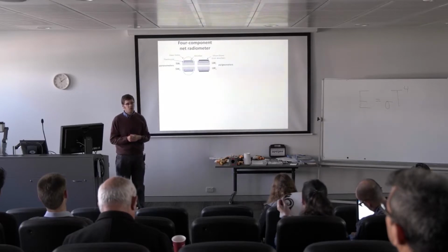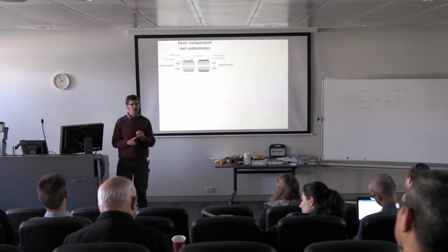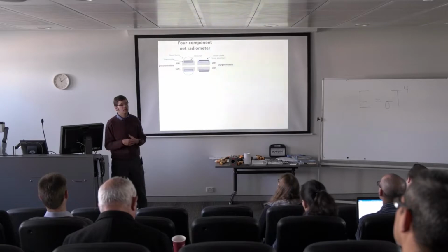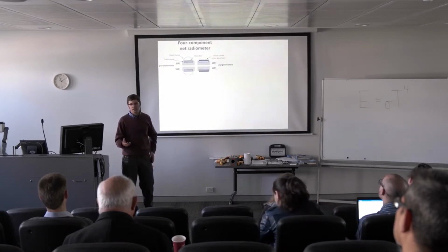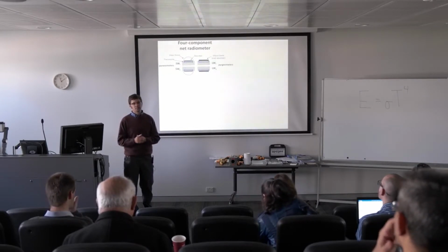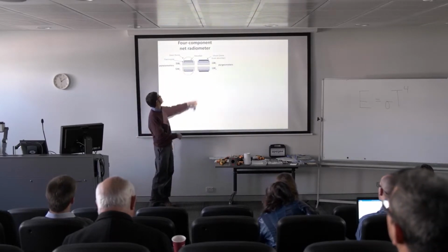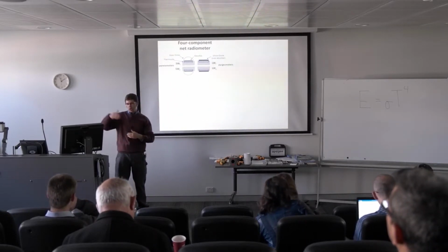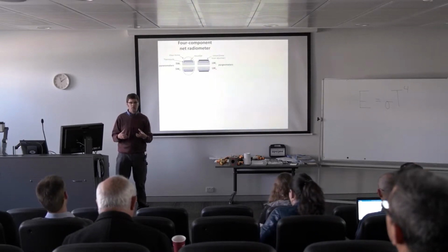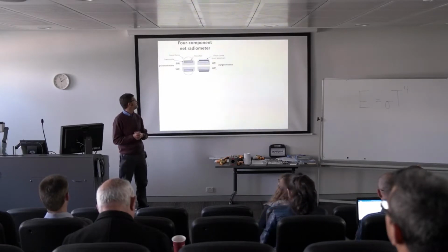The reason for the glass dome is twofold. One is to give it accurate cosine or angular response, and the other is to block all of the long wave radiation. So for a pyranometer, we're only interested in the short wave wavelengths. The glass is only transmissive to short wave radiation. So we have to put a glass dome over top of the black body so that it blocks the long wave, lets the short wave through. Therefore, the black body will only absorb the short wave, and the thermopile will only measure the short wave radiation.